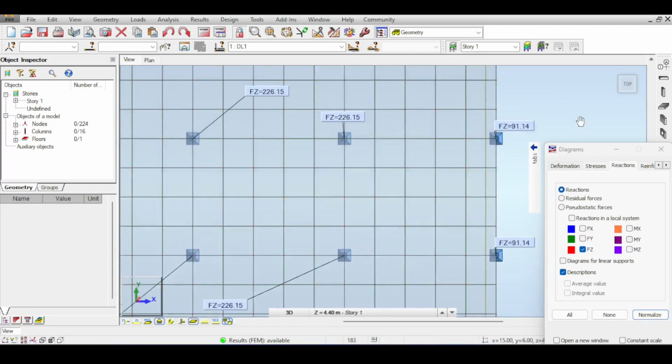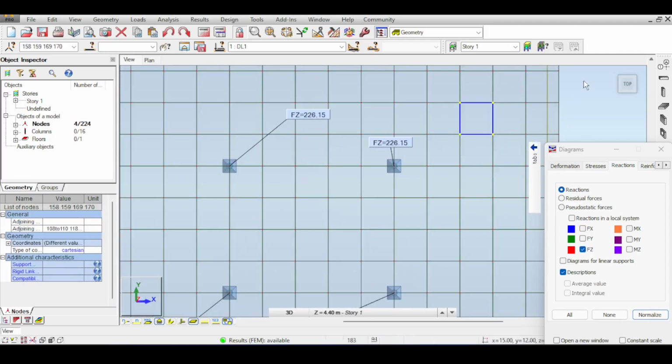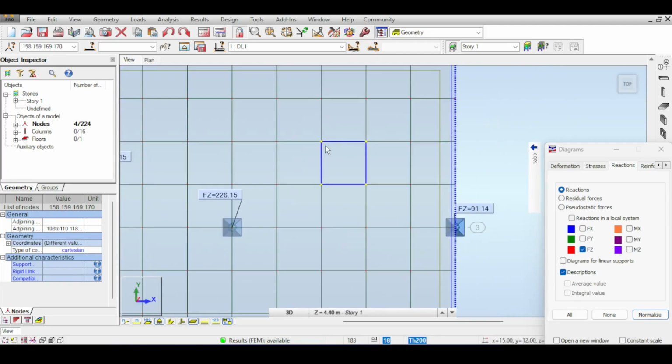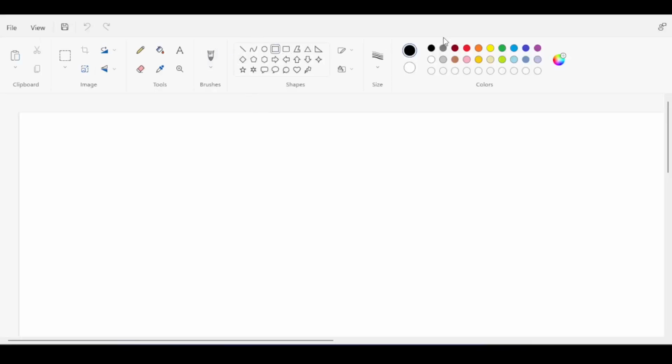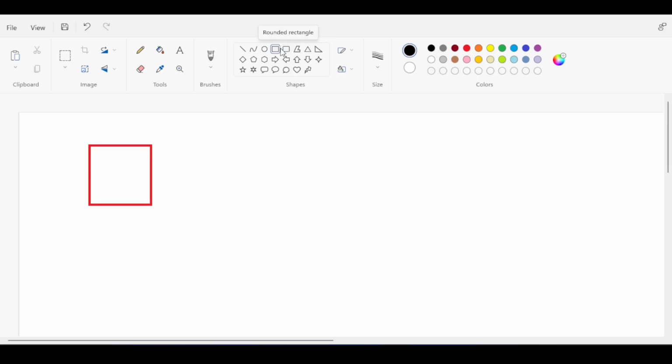But the idea is that plates are being discretized into smaller pieces that are your calculation units in the finite element method. Now, those little pieces are mapped to a benchmark piece. For the master's and PhD guys, you know this under the name of isoparametric calculation or isoparametric elements. You map the element that you have here onto the element that is a reference element.